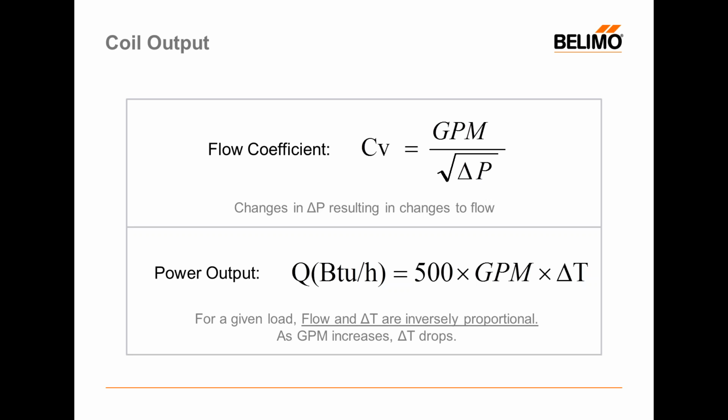So this is what we call, mathematically speaking, two terms being inversely proportional. So a 10% increase in flow requires a 10% reduction in delta T. And so you can see how we can easily get low delta T issues simply by over-pressurizing the control valve in our loop. So we've oversimplified this a little bit, but you certainly understand why overpressurization can cause some problems.